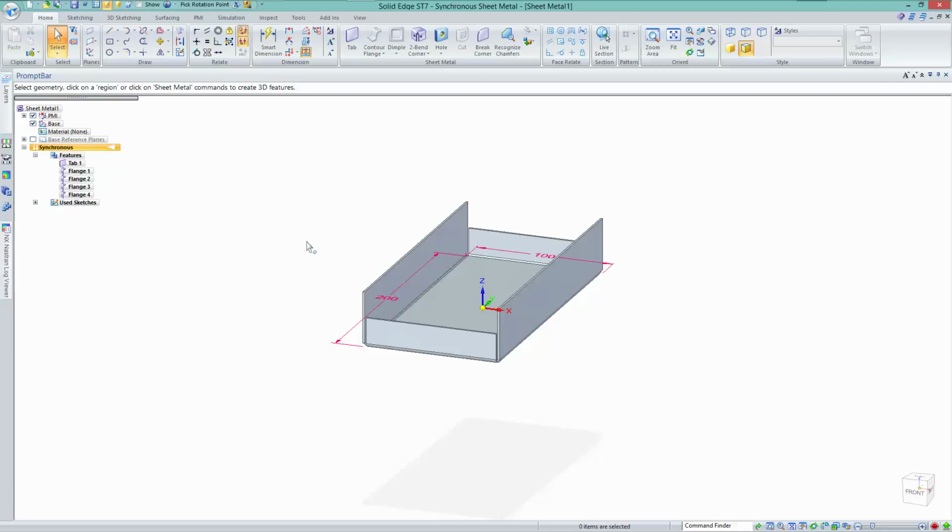So a couple of little keyboard shortcuts, and we can very quickly create a flange that's half the length of the first one. And again, we can select additional thickness faces. The steering wheel can be moved around. We'll touch on how that works in a little bit more detail in due course. And we can generate further flanges.